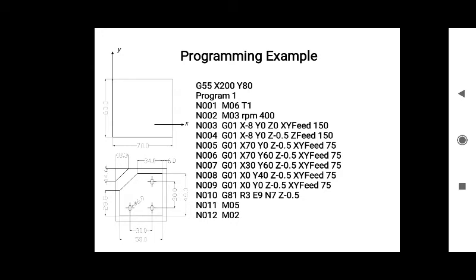After that this cut should be repeated, because only one cut is not sufficient, because we have given the feed 0.5 mm and the cutting depth is 4 mm. That means as 0.5 is already over, it should repeat 7 times.